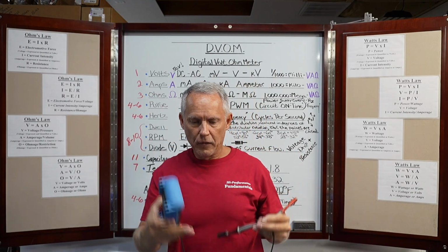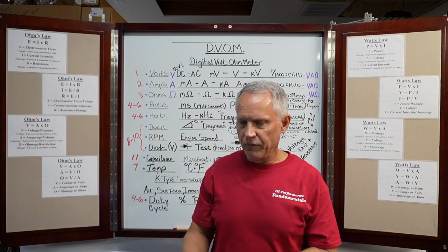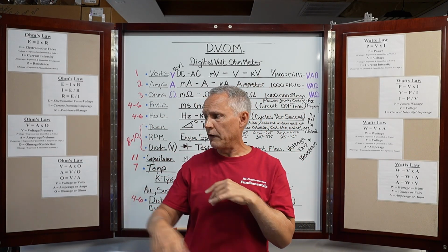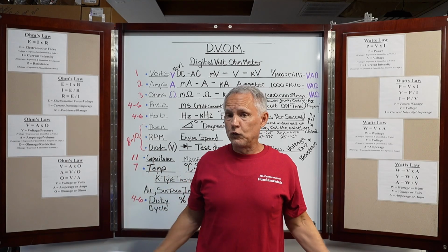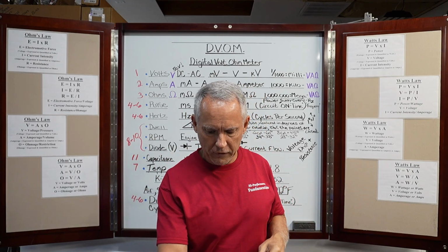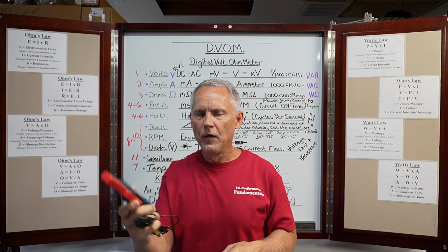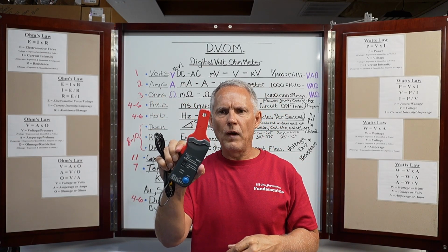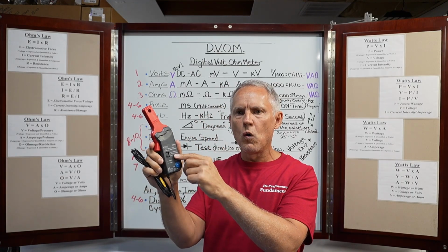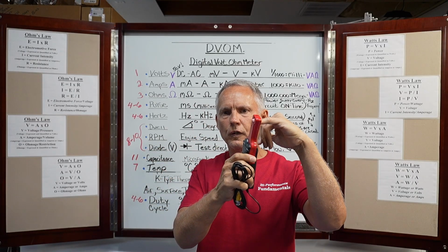So inline and inductive, all right? The beauty of an inductive ammeter is that you don't have to open a circuit. All you have to do is operate the circuit. That's great. So how does that work, right? Okay, so let's use the small one. This one says made by Pico, also a very good brand, right? It wraps around the wire. It's much smaller than the other. It's made for much lower current circuits, right? So it gets a lot closer to the conductor.